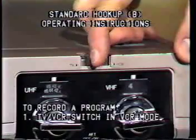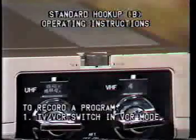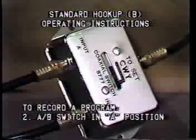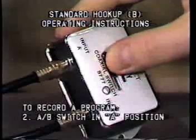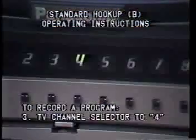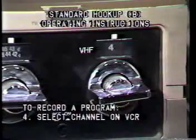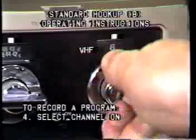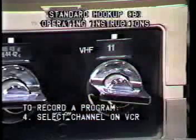First thing that we'll want to do, John, is to record a program. So the first step is to put the VCR output switch into the VCR mode position. And then the second thing we do is put the AB switch into the A position. Next, set the TV channel selector, or the tuner, to channel 4. Then select the channel that you want to record from on the channel selector of your VCR. You may have to tune the VCR a little bit to get the best picture.